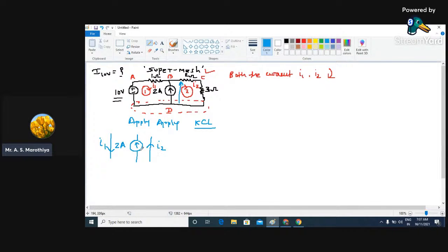Suppose we need to find the resultant. I can write here I2 minus I1 is going to be equal to 2. Here I have taken I2, which is moving in upward direction, to be positive, but obviously the downward direction has to be negative, and because the 2 ampere is upward, it is again positive. So I2 minus I1 is 2 ampere, which is in upward direction. This will be your first equation, which we got by applying simple Kirchhoff's current law in between the two meshes.